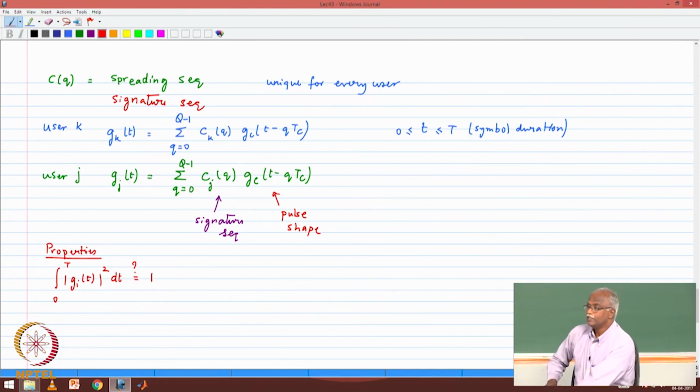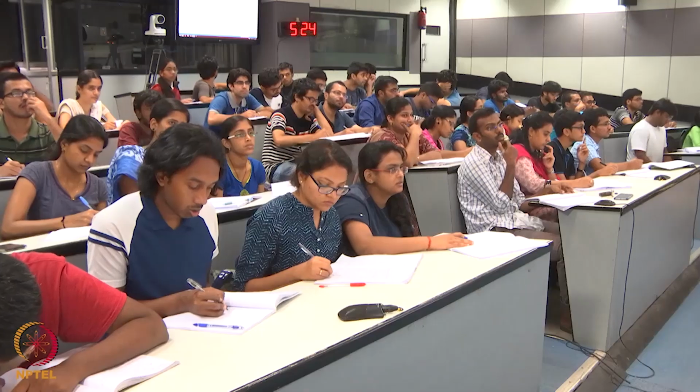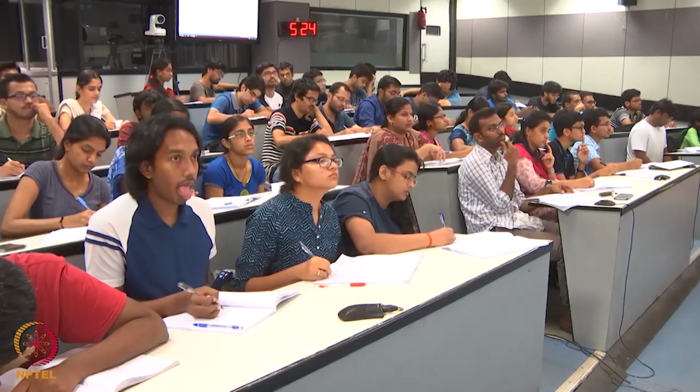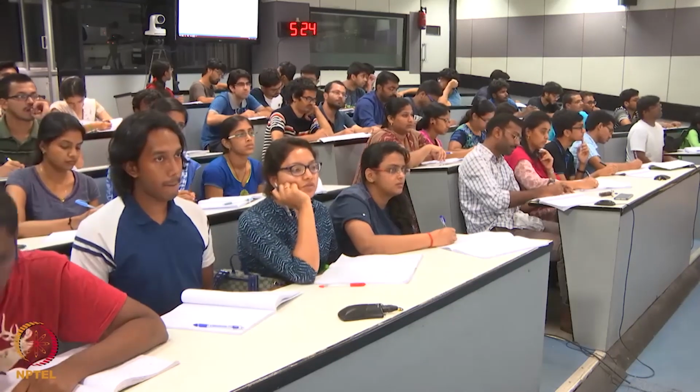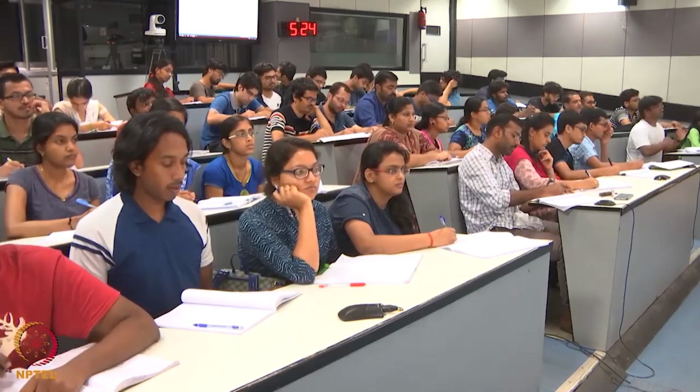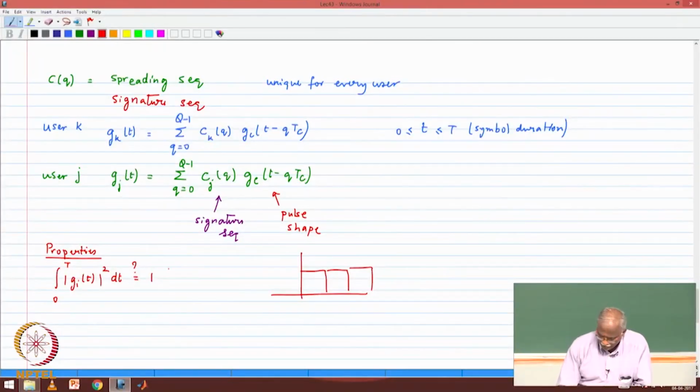Would you agree? Yes, because what is this? It's all these types of waveforms, right? If I take the magnitude squared and add, it will come out to be the right value. So yes, this is correct. This is one of the basic properties: the unit energy property is preserved, even after we do these. This is true for all of the spreading sequences as long as your sequences are plus-minus ones.